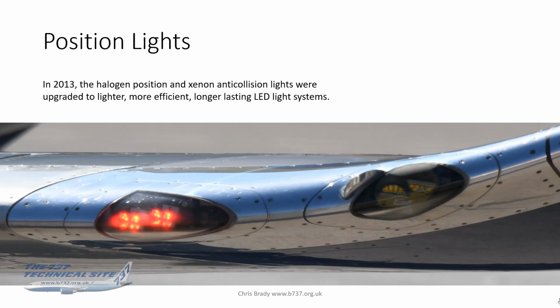But the position lights are what this photo is about, and you can see that there, it looks like 8 small LEDs there in 2 units, so much more reliable, much brighter, and if any one of those 8 were to fail, you can still dispatch. Whereas if it's a single bulb and that fails, then you're limited to day operations.